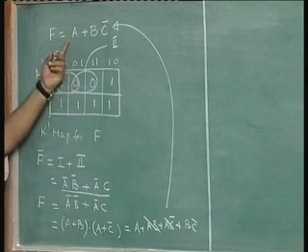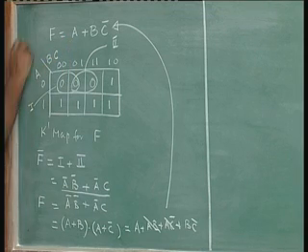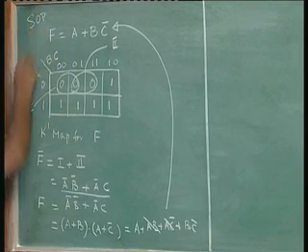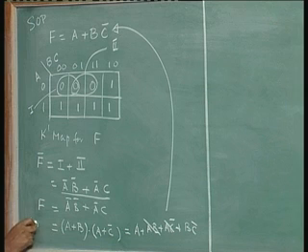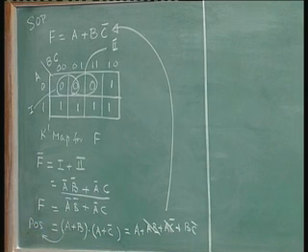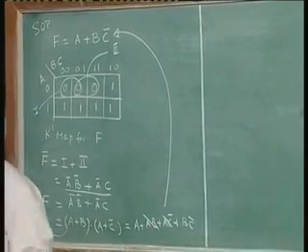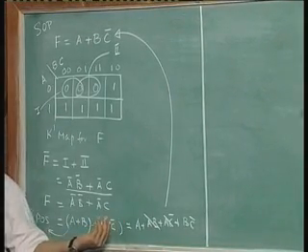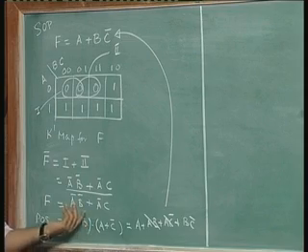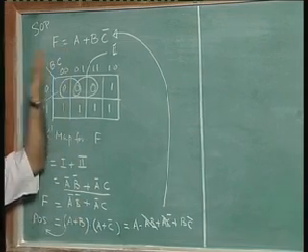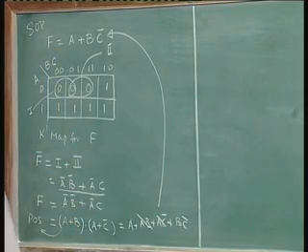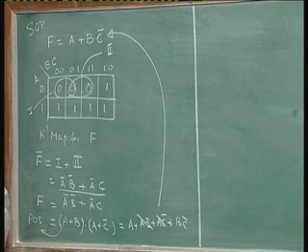This is a sum of product expression. This is a product of sum expression. So, if you want the solution in the product of sum form, I would stop here and use this expression, the minimum product of sum. Just as you get a minimum sum of product expression using Karnaugh map, I will also get a minimum product of sum expression using Karnaugh map using zeros.